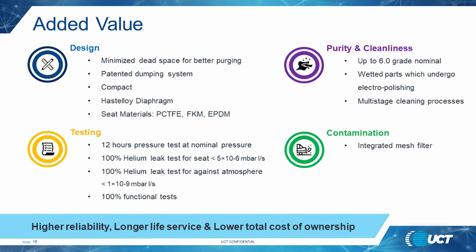Our design: minimized dead space for better purging, a patented damping system for better control, and a compact size. The Hastelloy diaphragm increases cycle life, gives high corrosion resistance, and has greater sensitivity. Seat materials: a greater selection of materials for compatibility and temperature.